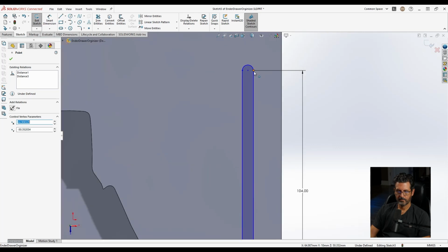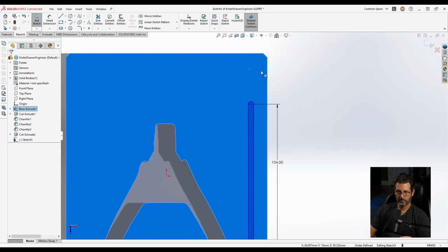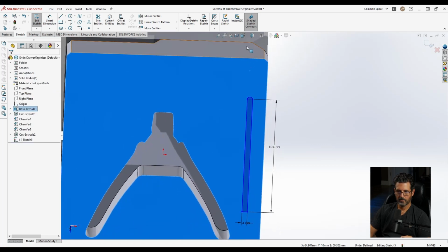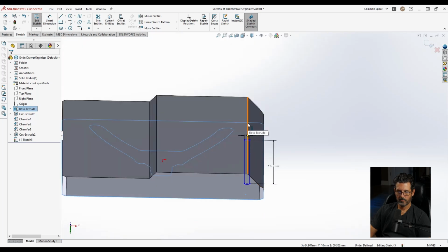We can check that though, because this leg of the Allen wrench is actually 20 millimeters. It just fits. So if we hit the chamfer at all, we're going to be in trouble, which means we're going to have to be to the left of that.